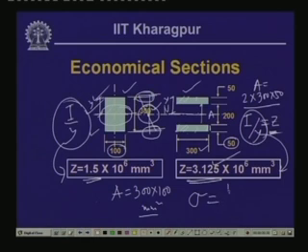And as we know that the stress sigma is equals to M y by I or M by z. So larger the value of z, then lower will be the stresses, and naturally if we know the allowable stress in the material, then if we can keep the stress level lower than the allowable limit, naturally that particular member will be more efficient. So larger the value of z, larger will be the moment carrying capacity, because the stress level will be lower, so we can put more load in such beams.